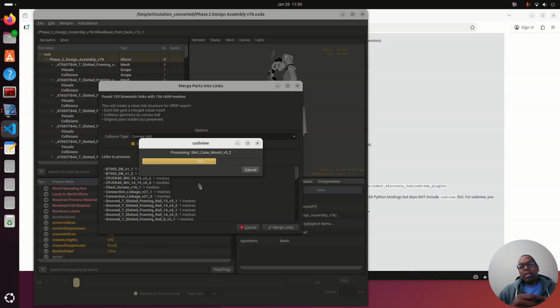The way to do that is to get the real robot, stick it up on a gantry or a rig, and then perform those same actions, send the joints and timings and all of that back to the model, and update the model with that. Otherwise, you're just playing in the simulator, and it's not going to directly transfer to the real robot.